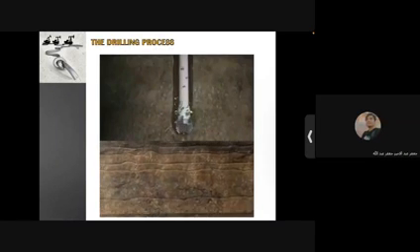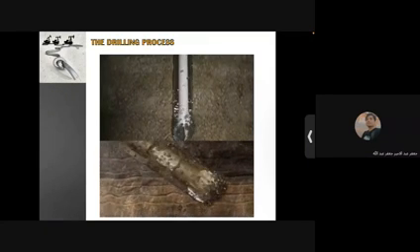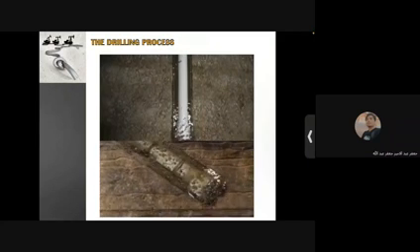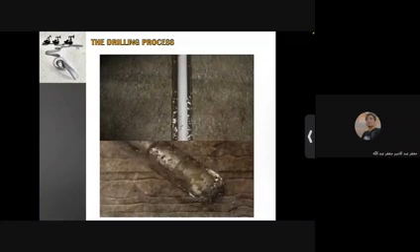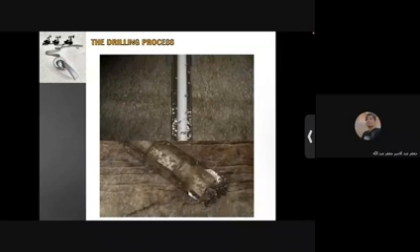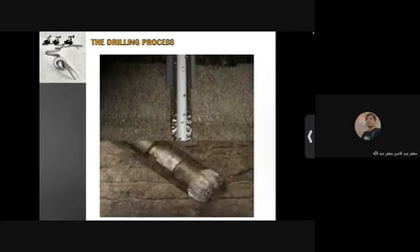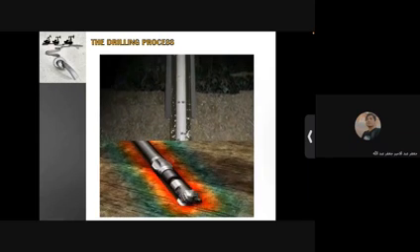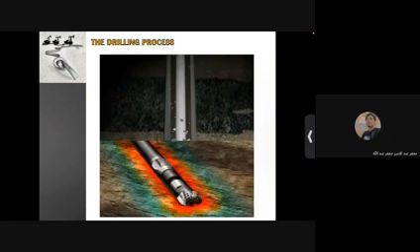The drilling process. The drilling process is as follows. First, mud or drilling fluid is pumped into the well, and then the drill bit starts to run. This is done by transmitting torque from the top to the bottom of the well. The drill bit breaks the rocks into smaller, shattered pieces, so the drilling fluid can lift these rocks upward and out to separate them from the drilling fluid, then pump the fluid back into the well. And also the hydrostatic pressure that belongs to the weight of the drilling fluid helps to maintain the balance in the well, as you can see in this animation.